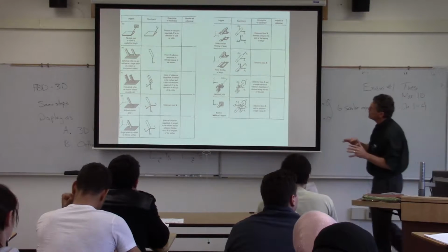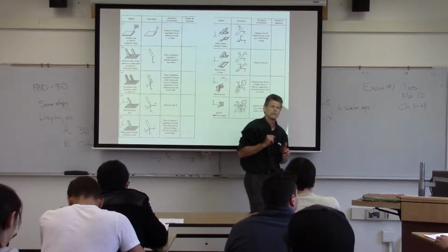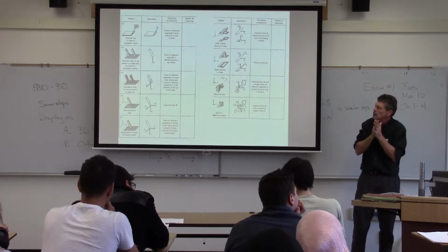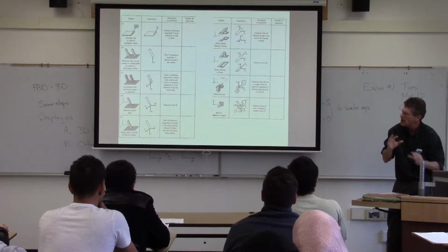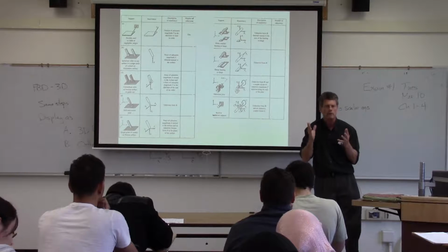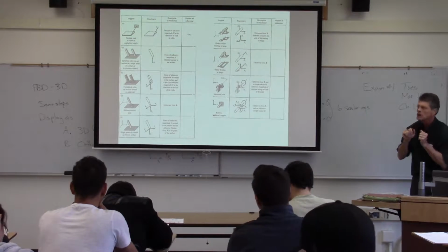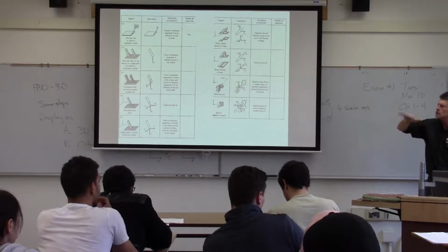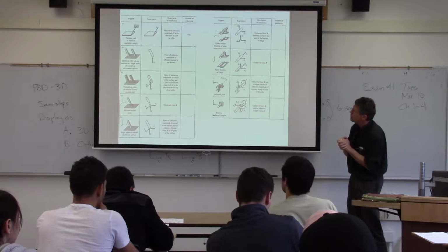Okay, so again, we're going to talk about some very similar things. We may have a plate or something that's being held by a cord. The nice thing about a cord is we know its tension, and we know it has to act along its line of action. But we need to think about how many unknowns are going to be provided. In this particular case, it'll just be the one, because we can establish the direction. We usually have either a set of angles or a couple of points. We can go through that process of creating the unit vector, expressing the force along that direction, and then solving for the x, y, and z scalar components.